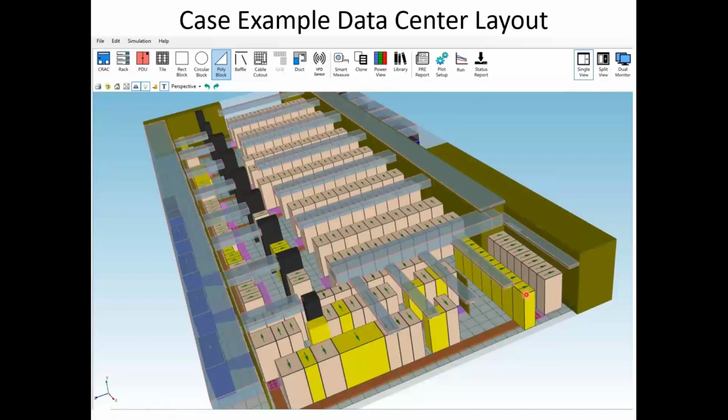And you'll notice airflow direction here indicated by green, and you notice it's not optimal. In some cases, we have things pointing right at each other. If you take a look here, this is what we call classroom style, all inlets facing to the front. So this one's dumping heat into the intake of the one behind it. Not a good thing, and sucking heat out over here. So the hot air from this server has to go up over the top and go up and out. Not a perfect situation. Guess what? A lot of data centers aren't perfect. Over here, we have a similar problem. These are blown against the wall, and there's not much pulling the air out there.